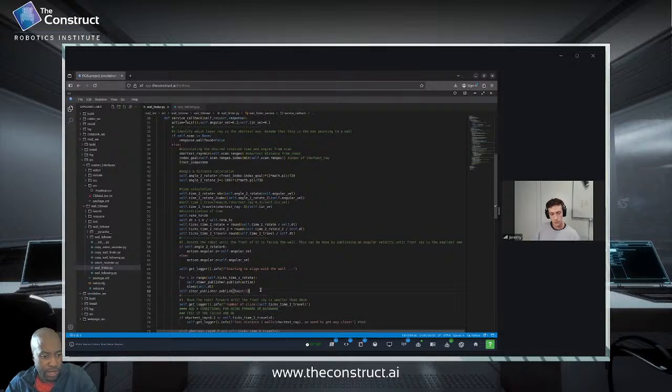So this was supposed to be implemented using an action, but the way you implemented it is seemingly some kind of mix of topics and services, and then you're having to publish command velocities on a particular topic. It does work, it's just not the recommended way of doing it, but for the purposes of what we have seen so far and its capabilities on going around the track, it is satisfactory, I would say.